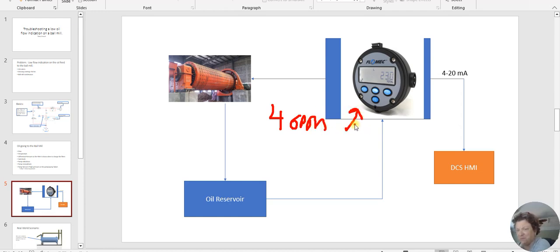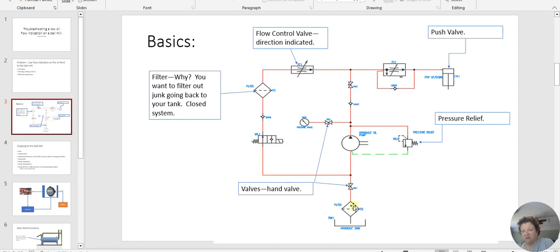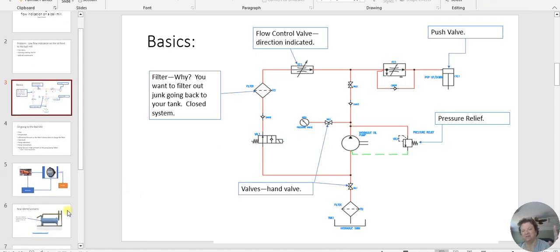You have to make sure that your instrument is set up properly for the flow, and that can get that granular at a low flow. It's a super low flow to be able to monitor. That's why they use the paddle, because the paddle doesn't care how slow it goes, but sometimes the components on the inside are too plasticky, or they get ate up for whatever reason, especially if you get particles coming out of here that are going back through, like in this feedback going into the hydraulic tank or oil tank. If it shows back up down here, and your flow meter is after your pump, you're likely to see material coming into the flow meter, and you're at risk of having it break down. So those are the types of things that you got to keep in mind when you're troubleshooting something as flow.